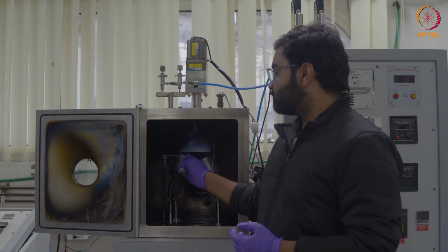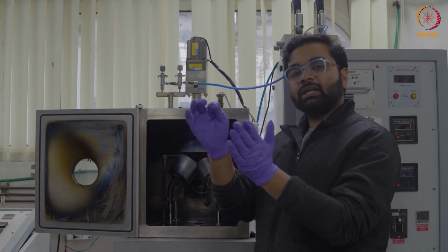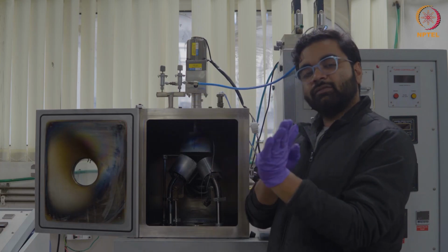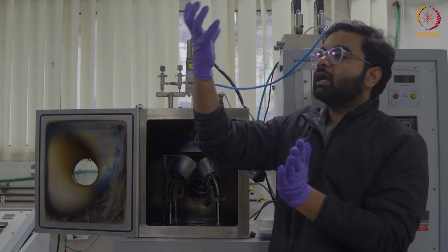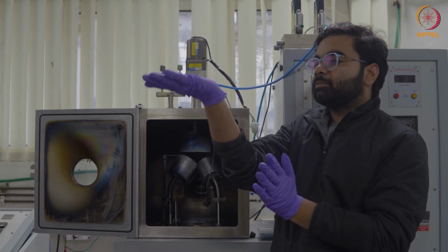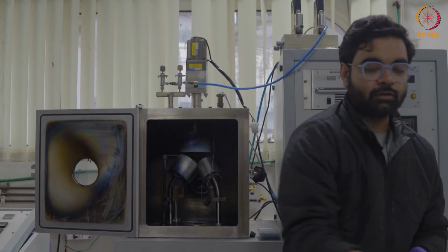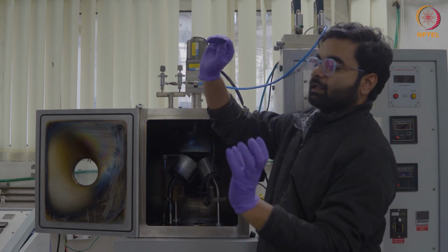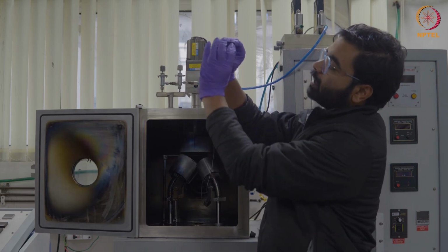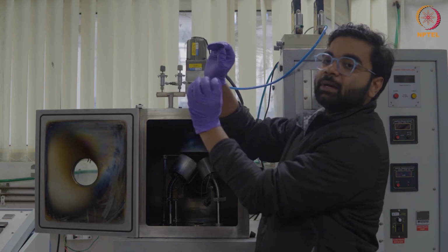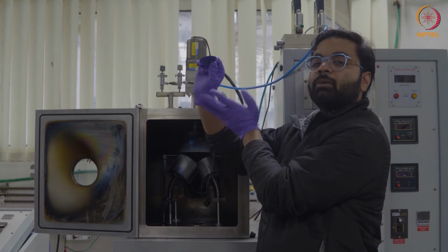Now once the argon comes into this chamber, it will act as a stone, and it will come and strike the surface. As the argon strikes the surface, it will eject the material from there and the material will go out and start getting collected on the substrate that we have created. The substrate is the coated silicon wafer, which we will place here. Suppose you are using silicon carbide, the silicon carbide will come out and slowly get deposited. It will be atom by atom deposition on the surface, and then appropriately we get the thickness.